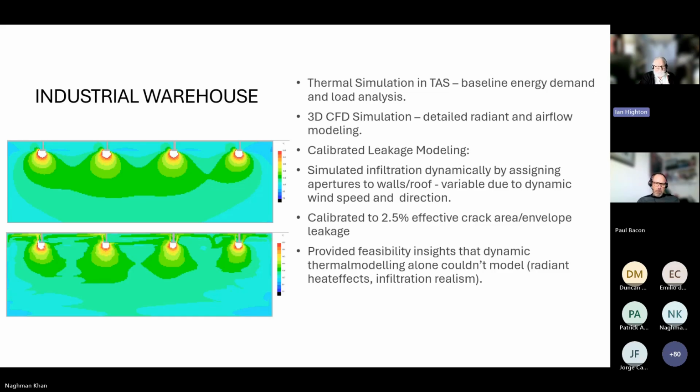The other thing as well is real buildings have far greater thermal bridging and edge loss effects. So again, you just have to change your regulatory type model to account for all of these actual real world imperfections. I always think of the regulations as a perfect target because it's perfectly built, perfectly constructed, perfectly occupied, and the plant works perfectly as well. Whereas once you get to a real building in real life, everything's wrong. Well, not everything, but that's where these massive discrepancies come from. Sorry, went off topic a bit there.